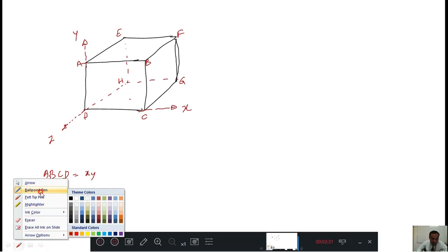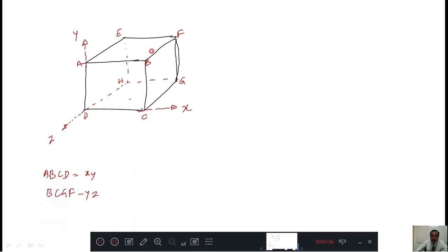On this three-dimensional body, we can put some forces. Those forces will be perpendicular to the plane, perpendicular to the BFGC plane, and this I can call sigma x. Another reaction force will again be sigma x, equal and opposite, to say it is in equilibrium.